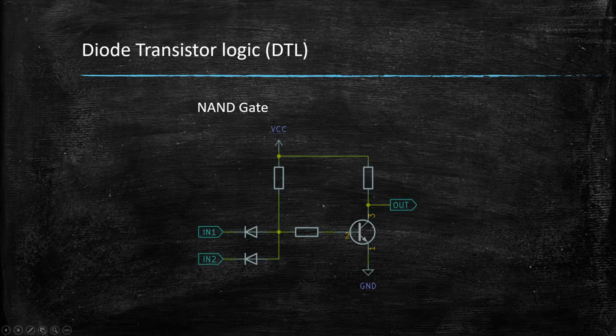Yeah, so this circuit has some issues. As you might notice here, if both of our inputs are high and we were just coming from a low state and we have to switch our transistor over, the charges that are going to be in the base here have nowhere to go. They can't flow reverse bias through those diodes, and they have a pretty big resistor here. And so our transistor will take a long time to switch out of saturation and into non-conductive mode.